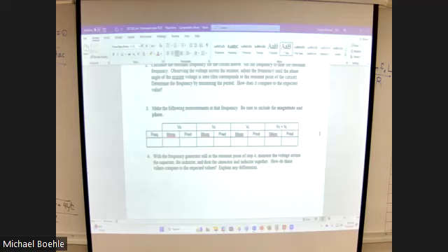And we're going to actually deal with that reason a whole lot more next week. Because components have resistance. Well, specifically, the inductor. Capacitors, especially our small mylar capacitors, are really close to ideal. They act very ideal. Inductors, not so much. That's really where most of the problem is, because I can't make an inductor, especially a lot of inductors, without lots and lots of small wire wound around to create the inductor, and thus giving me some amount of resistance. Anybody remember what the resistance is of your 100 millihenry inductor?